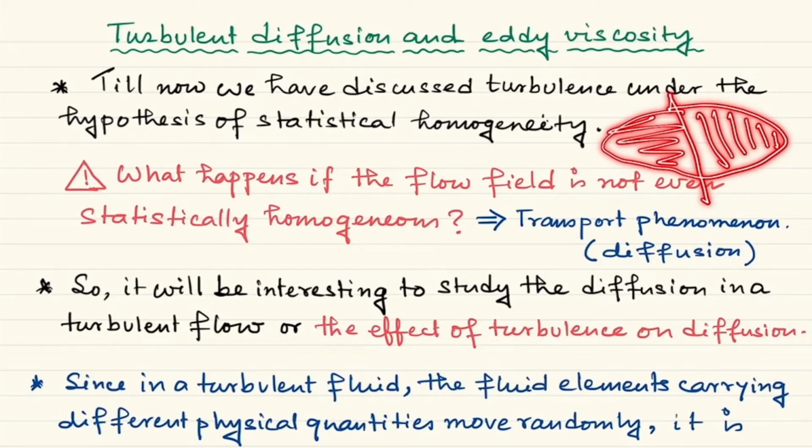In this case, you can say that the turbulence over here cannot be put together with the turbulence over here in a global homogeneous framework. So then you have to take subdomains like this and this, and within each subdomain you can think of homogeneous turbulence.